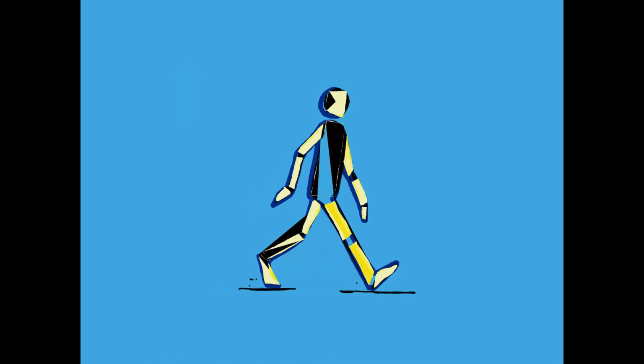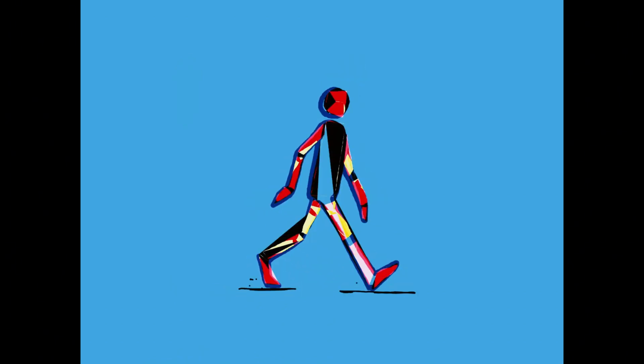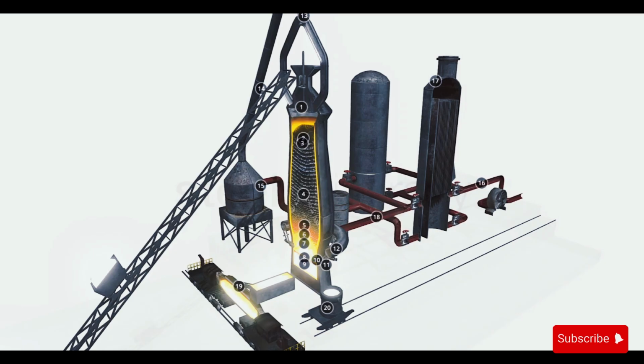Let us have a look at what happens at the different parts of the blast furnace during the extraction process. Hematite, an ore of iron, is mined as iron(III) oxide. The iron(III) oxide obtained is then ground into a powder and mixed with limestone and coke. The mixture is then fed into a blast furnace from the top.